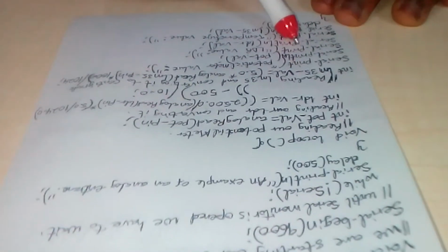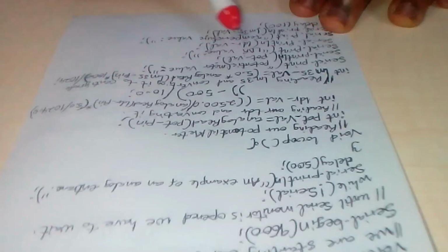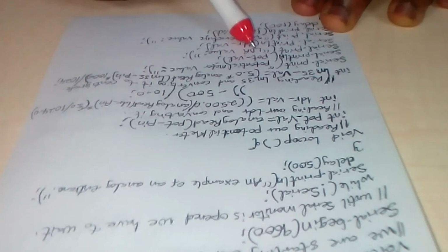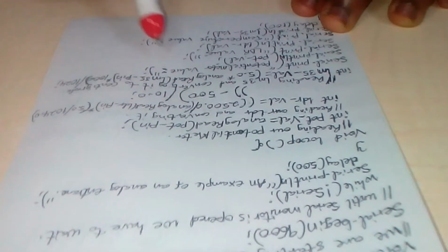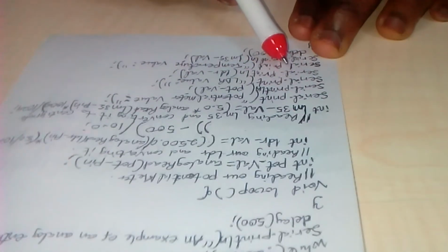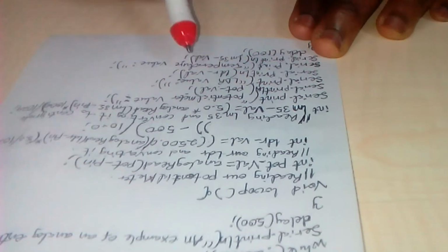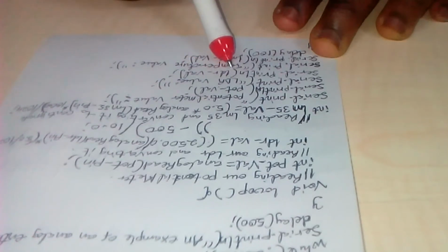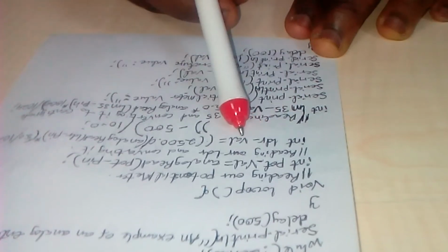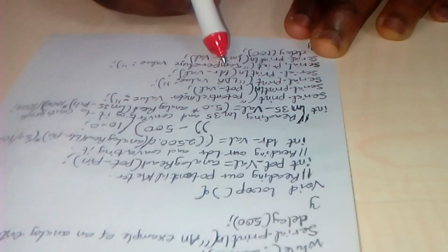And we have our Serial.print, okay, LDR value. We write the LDR value. You can actually write what you want, but writing LDR value will be very good because we are dealing with light dependent resistor value. Now we say again Serial.println. Why do we say Serial.println? That means it should be in a new line. Now we have LDR value, as we can see here. That means it has converted it to digital.